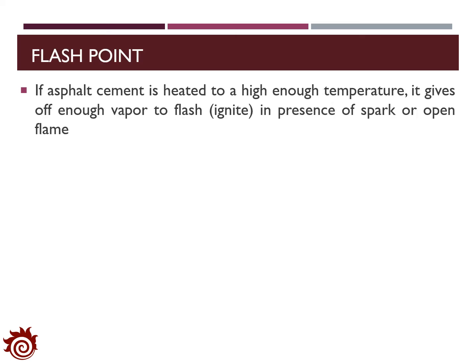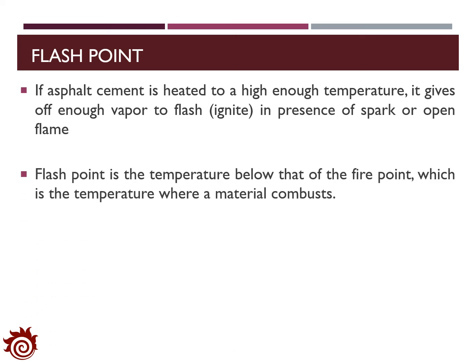In asphalt cement, if it's heated to a high enough temperature, it will give off enough vapor to flash in the presence of a spark or open flame. The flash point is then defined as the temperature below that of the fire point, which is also the temperature where the material combusts.